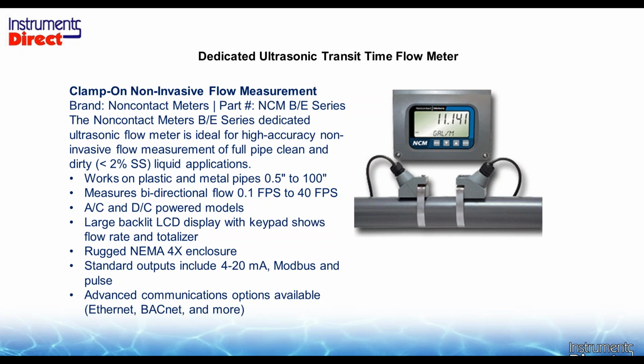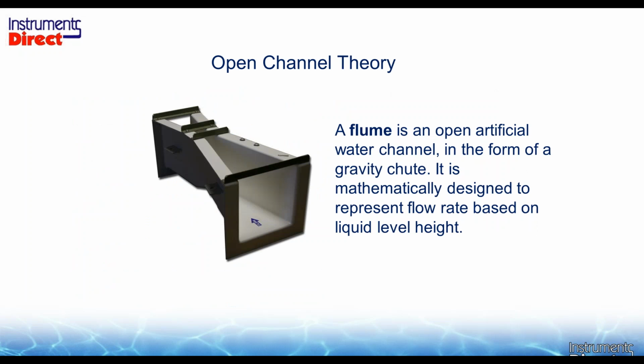So if you have something that's using Modbus, RJ45, or if you need something that's using BACnet, something that's using Ethernet, the communications are there, and you can just plug in the meter, and you'll have the communications you want to communicate to your building automation system. So again, it's making accessibility to sub-metering very practical, economical, and adaptable.